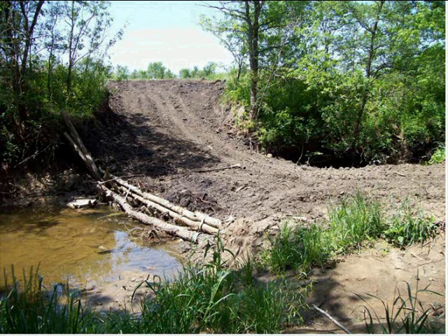Improperly designed and built low water crossings block aquatic organism passage, such as shown in this picture. However, like other road stream crossings, such as culverts or bridges, low water crossings can also pose a risk to livestock and equipment and cause chronic water quality problems. Low water crossings can be built with many types of equipment commonly found on farms. Front-end loaders or a blade on a three-point hitch can easily be used to push material around and into place across a stream. However, unless a ford is placed at a site that offers natural stability and built according to a few design principles that work with instead of against the stream, it may not persist over time.